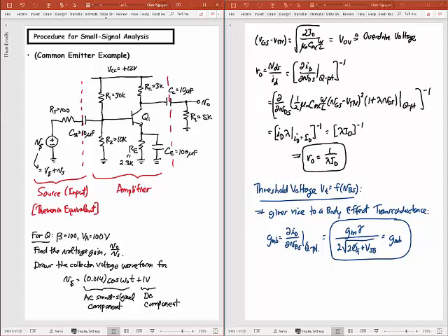So my bipolar transistor is doing amplification, and it's exactly what you think amplification should be doing. I may put a very small signal here. By the time I get to the output, it's going to be a much larger signal. So what's happening is this source consists of a DC component, this V sub S there, and an AC component, v sub s there. And so this really looks like this. That's time, and this is that V sub S. I have the line down it to say that's a capital S. Okay, so it looks like a money sign, but it means I'm trying to make a capital S.